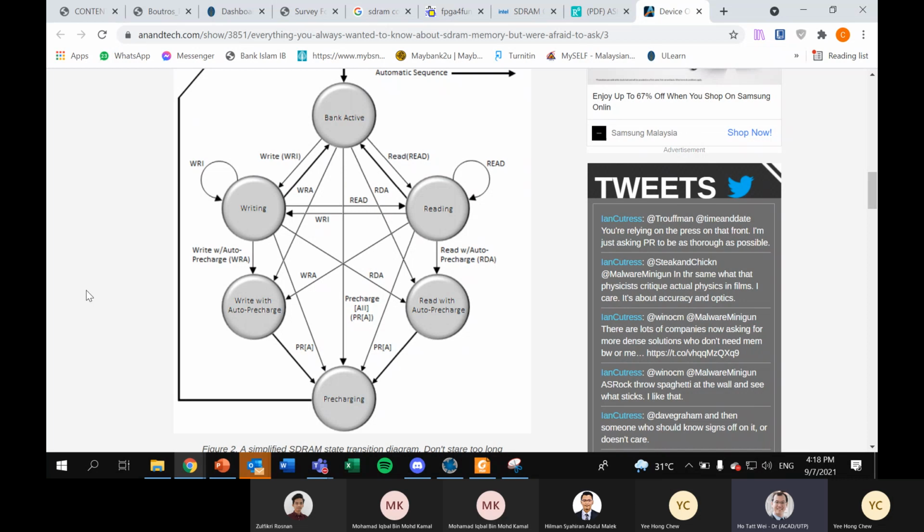There's a specific reason why I just want you to do burst. With burst, you get the idea that you have to handle multiple data coming out, or send multiple data in over a clock. So it's a bit complicated, but I want you to do a pre-charge after that and simplify it. If you know how to do these two, you will be able to design the circuit to do the rest of the transitions. It's somewhat similar, you just have to pay attention to the logic.